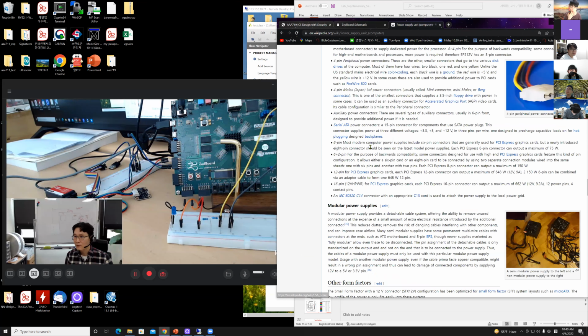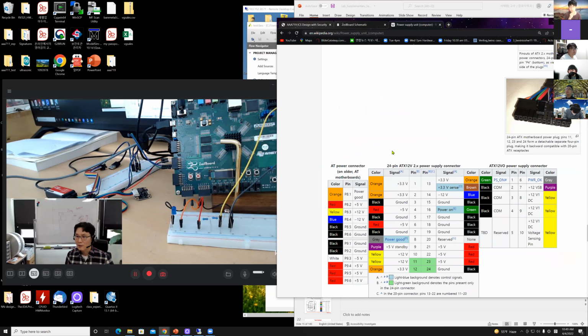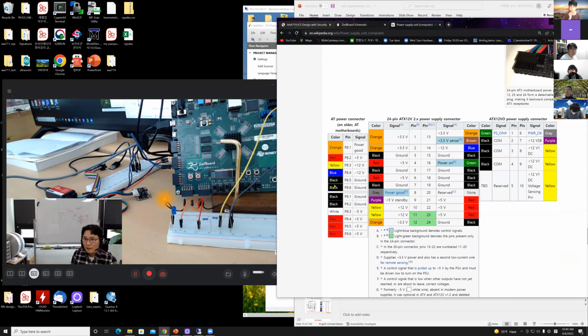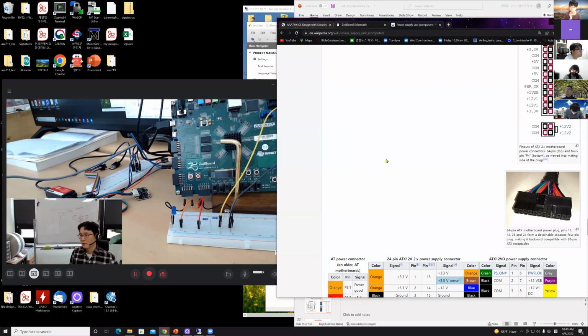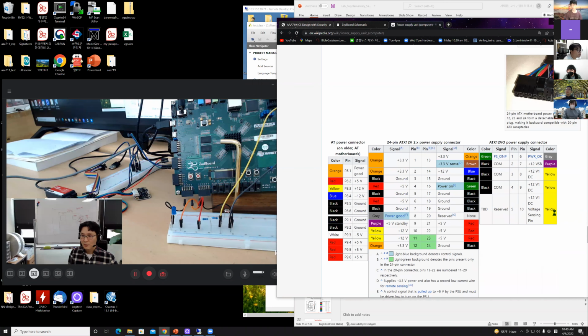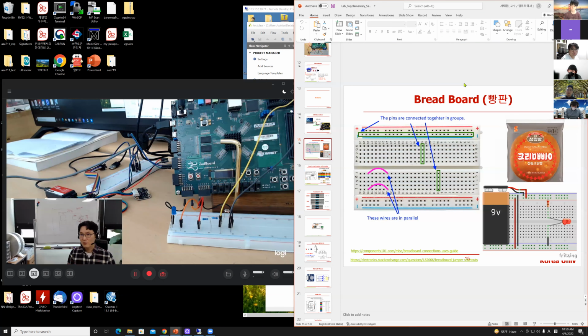Okay, here. Black. So here, the power supply in a computer, right? You have black, red, yellow, and so on. Typically black means ground. Ground is 0 volt. Red means 5 volt. Yellow typically means plus 12 volt and so on. So we use that convention. It is better to stick to that convention when you are creating your custom circuit.